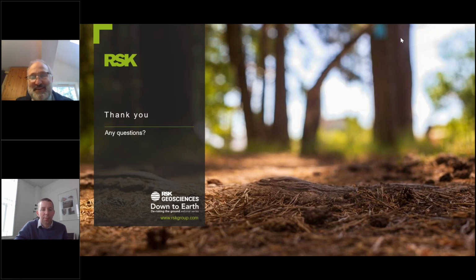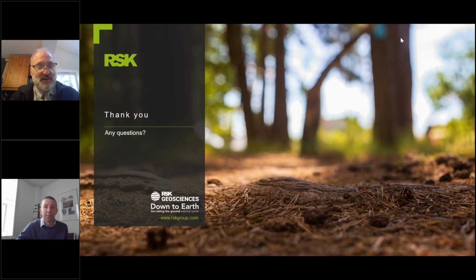Well, that's a good question. It sort of depends. It depends on the site. It depends on the materials. I think generally with nuclear density gauges and electromagnetic gauges, you'd probably be working on either a 25-meter grid for your layer, or maybe a slightly tighter 20-meter grid.